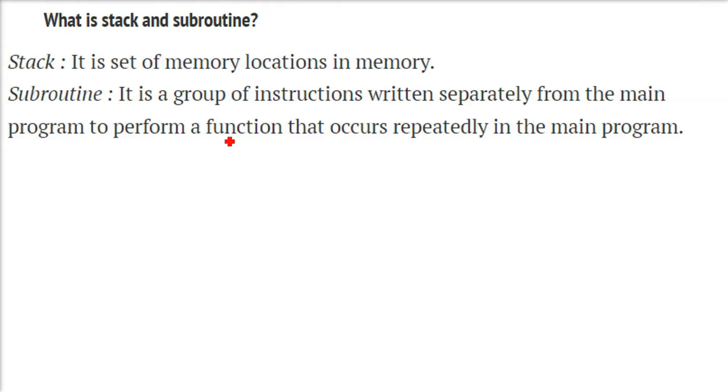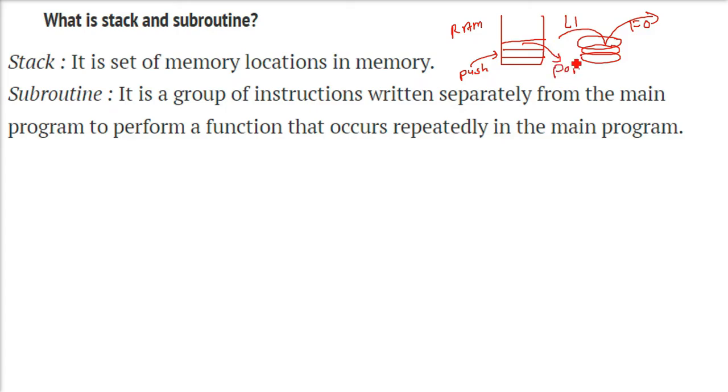What is stack and subroutine? Stack is a temporary memory location in the random access memory, RAM, for temporary storage of data or the return addresses, like a stack of plates. The last plate to be put is the first to be taken out. This is the concept. When we implement it, we use a certain instruction, LXI SP, like that. The stack is created, one by one we put the data, and then we pull out the data. So pushing is populating the stack, and popping is depopulating the stack.